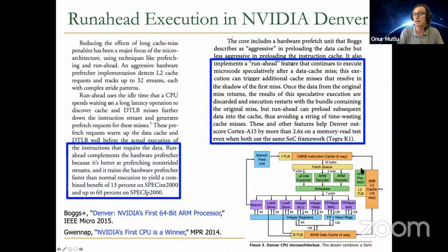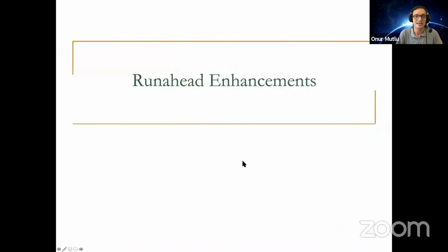And you can see that there are already multiple forms of prefetching. And I would recommend reading it because it actually shows how they do micro-coded binary translation. They actually do compilation into a 7-way superscalar processor in a binary translation engine. So they take the 64-bit ARM code, they translate it into a 7-way internal superscalar microcode, micro-operation format. And yeah, if you're interested, you can take a look more.